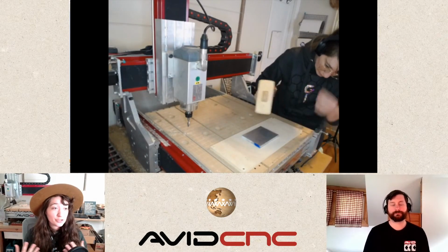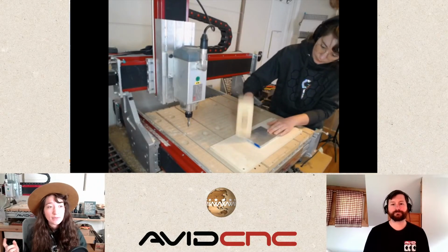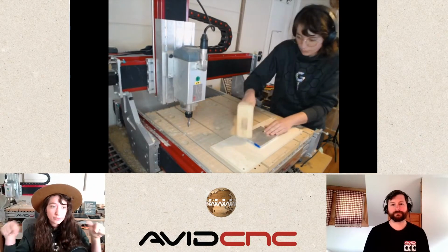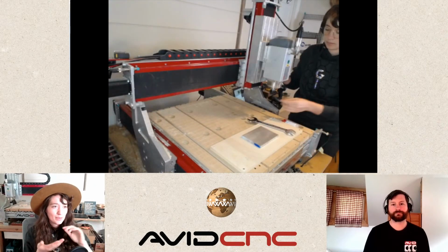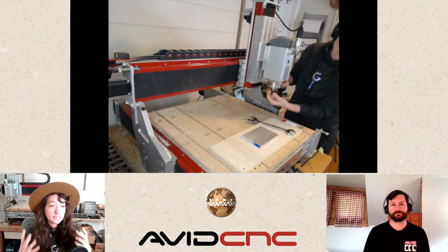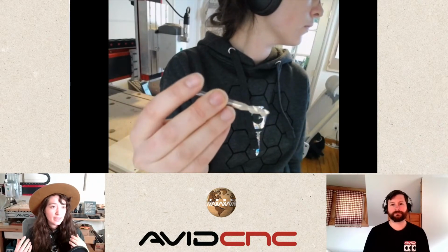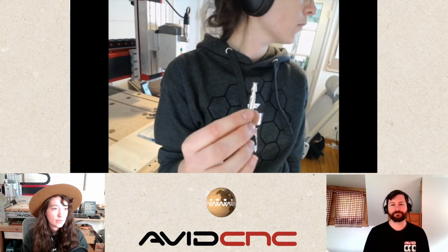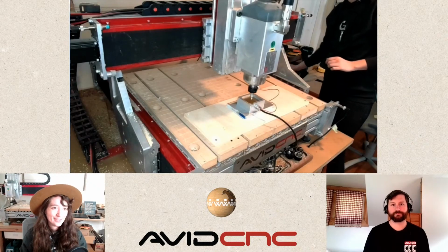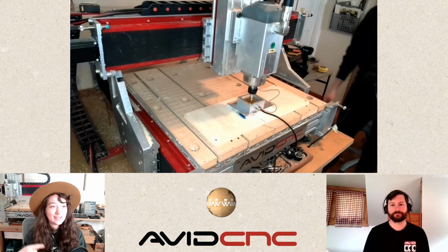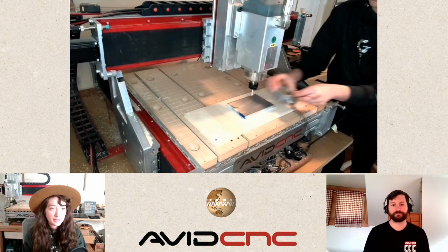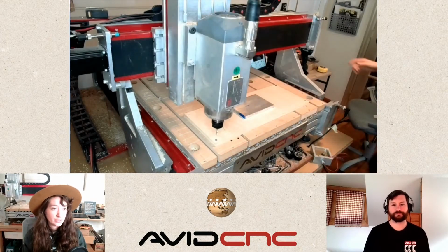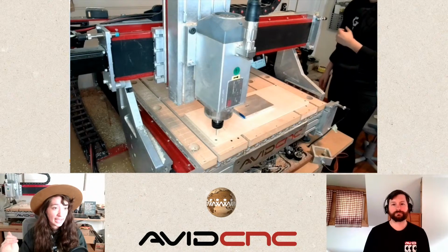So here I'm just doing a pressure fit. I had thought about doing blue tape inside of my little pressure fit jig and then blue tape on the bottom of the aluminum. But when I did this test fit, it was so snug, I knew it wasn't going to go anywhere. Here's the bit that I used, 1/4 inch, with the ZR coating. I was trying to get it to focus there. So now I'm going to set my 0 to the material surface of the aluminum. My XY is still set to the corner of my jig though, because that's just what I chose to do. So I'll reset the Z to the material height.